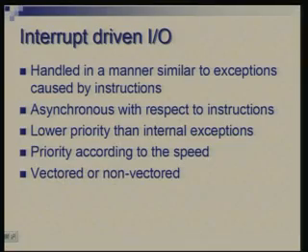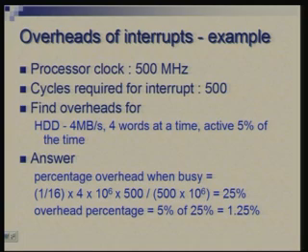Similar to internal exceptions which we discussed earlier, the mechanism could be vectored interrupt or non-vectored interrupt. Vectored interrupt means that the control directly gets transferred to an exception handler which is meant for a specific exception, and in the non-vectored case you set the cause of exception in a particular register, but transfer of control takes place to a specific location, and then you run some code, check that cause register and branch off to one of the points. So, both the possibilities exist here also.